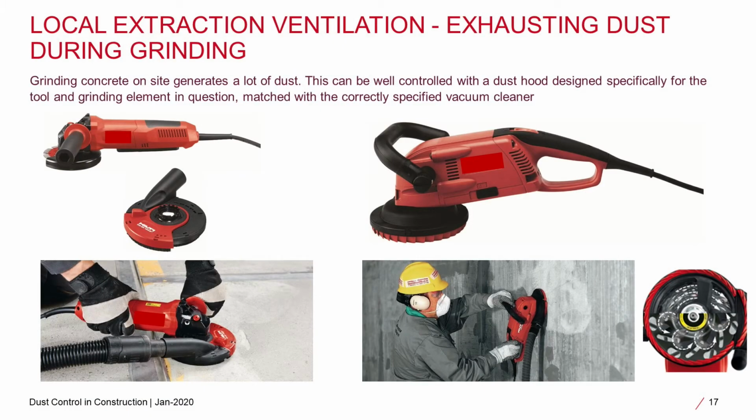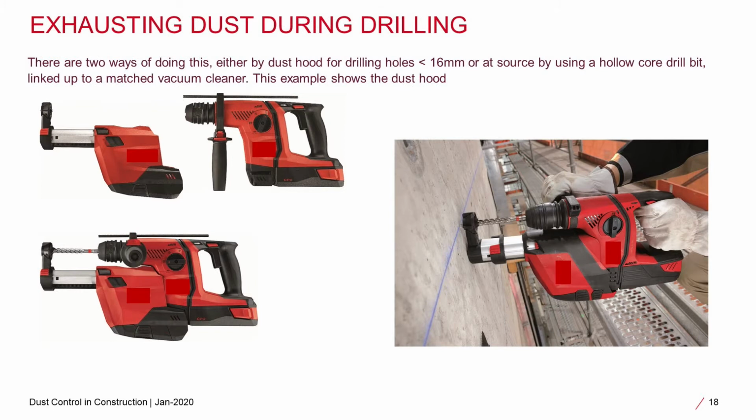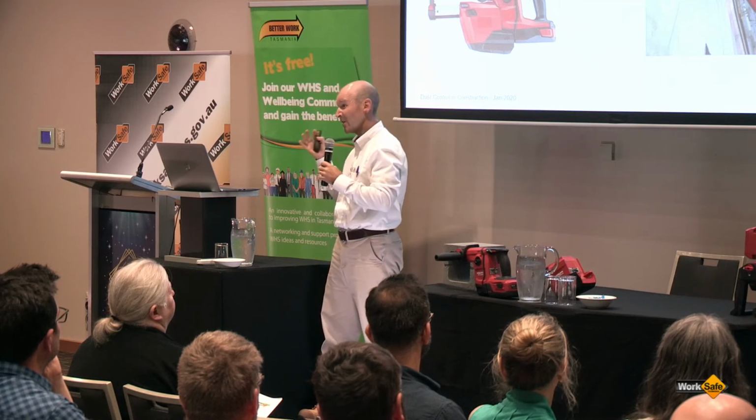Grinding is a very easy problem to solve as well, just by fitting hoods to existing tools or by getting specialized concrete grinders. And then exhausting dust during drilling. This is again for the services trades, and is a very easy problem to solve as well. We're talking about plumbers, electricians, builders doing renovation work. Again, it's a watch-out because it's in an enclosed space and particles can build up if they're not being captured at source. So with the help of my colleague Neil, we're going to do a very quick demo and I'll show you the efficacy of these kinds of products.